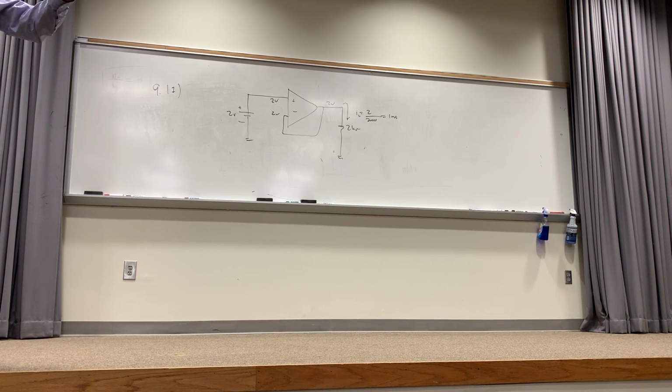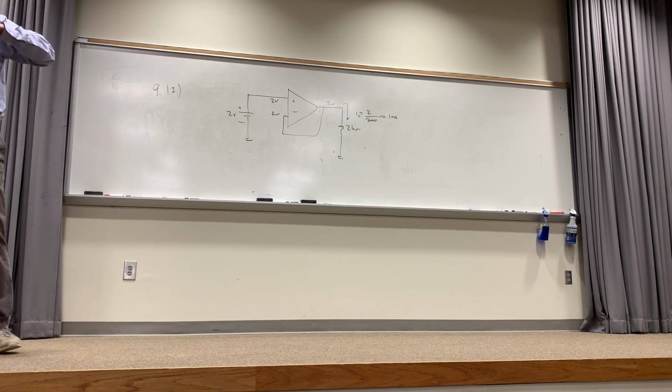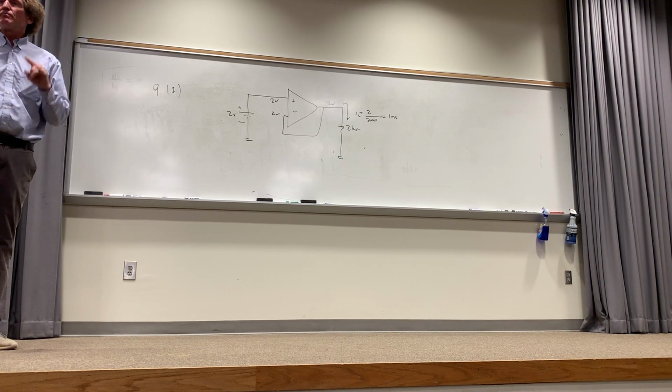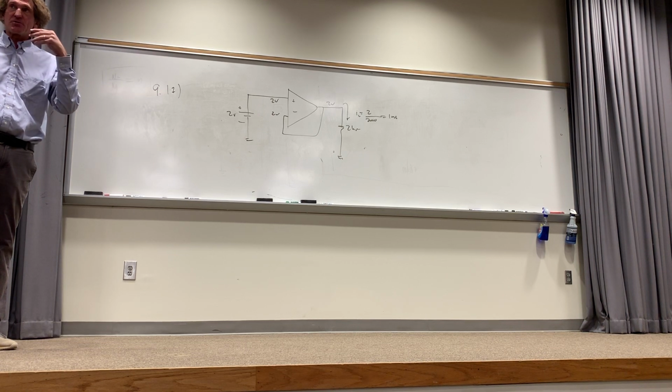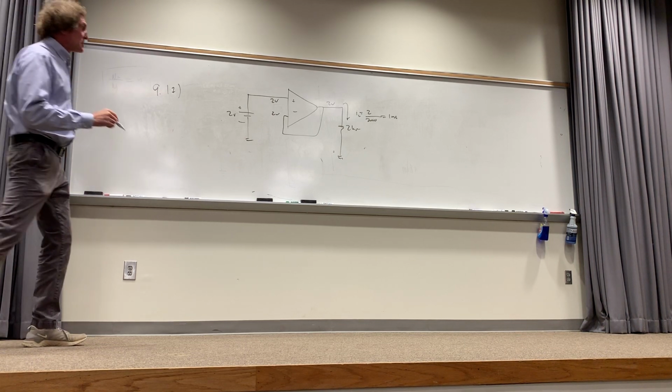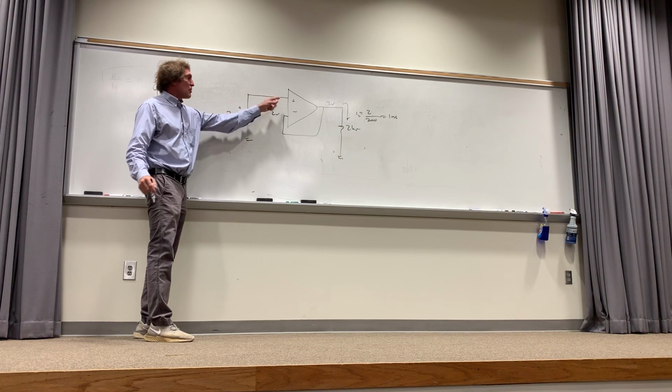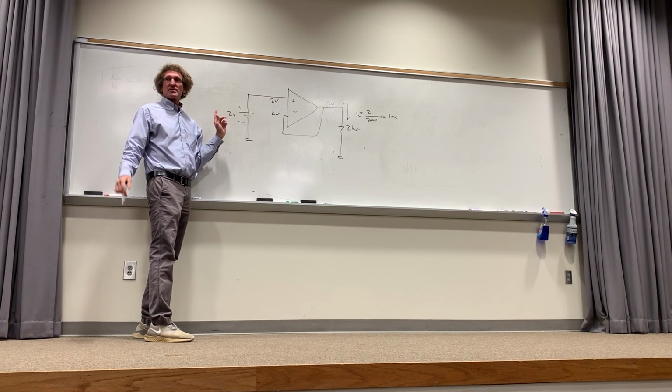It means if you try to get any signal out of there, and you don't first use a follower circuit like this, you won't be able to get it, because the thing you measure it with has a much lower impedance. So all the actual sensor voltage will be developed internal to the sensor. Just try to appreciate what I'm telling you. So what this is, no current flows basically from this. Some does. It's called a trickle current, but it's in the noise. You don't worry about that.